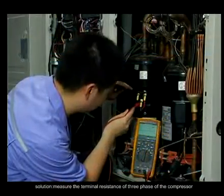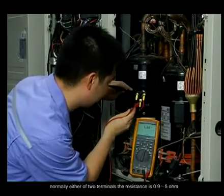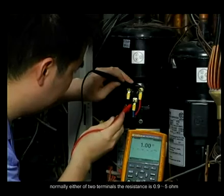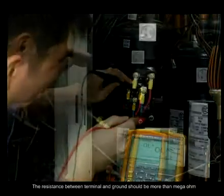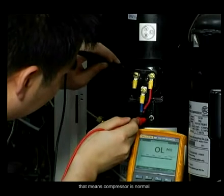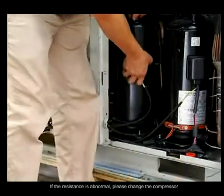Solution. Measure the terminal resistance of 3 phase of the compressor. Normally, between either of 2 terminals the resistance is 0.9 to 5 ohm. The resistance between terminal and ground should be more than mega ohm. That means the compressor is normal. If the resistance is abnormal, please change the compressor.